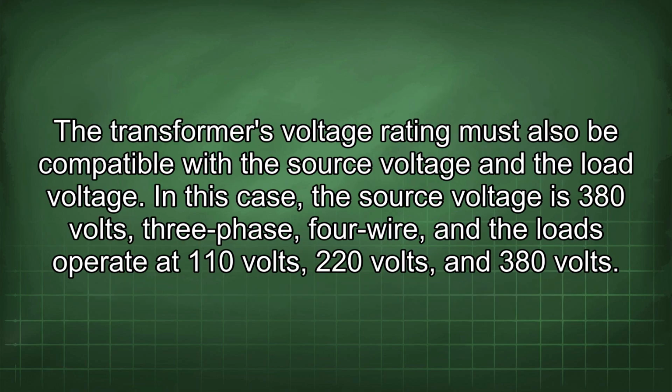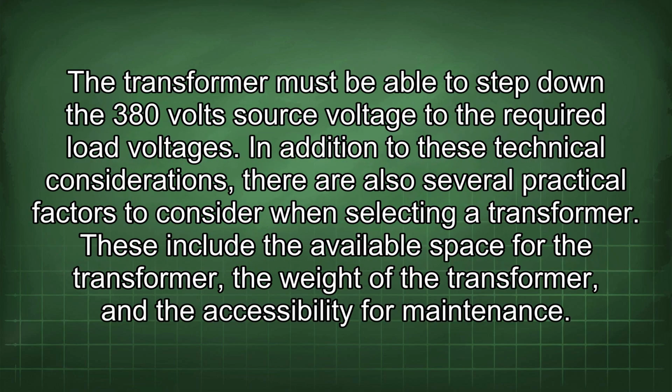The transformer's voltage rating must also be compatible with the source voltage and the load voltage. In this case, the source voltage is 380 volts, 3-phase, 4-wire, and the loads operate at 110 volts, 220 volts, and 380 volts. The transformer must be able to step down the 380 volt source voltage to the required load voltages. In addition to these technical considerations, there are also several practical factors to consider when selecting a transformer.